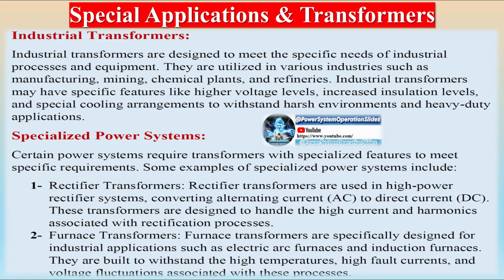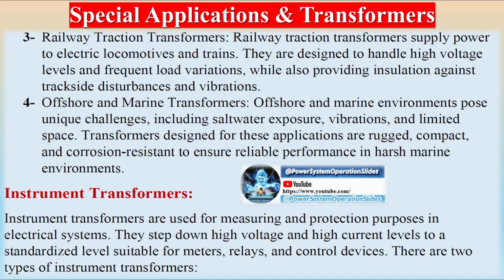To determine the power rating required for a specific application, factors such as the connected load, expected load growth, diversity factor, and power factor must be considered. Accurate load assessments and future projections are crucial to avoid undersizing or oversizing the transformer, which can impact efficiency and reliability.